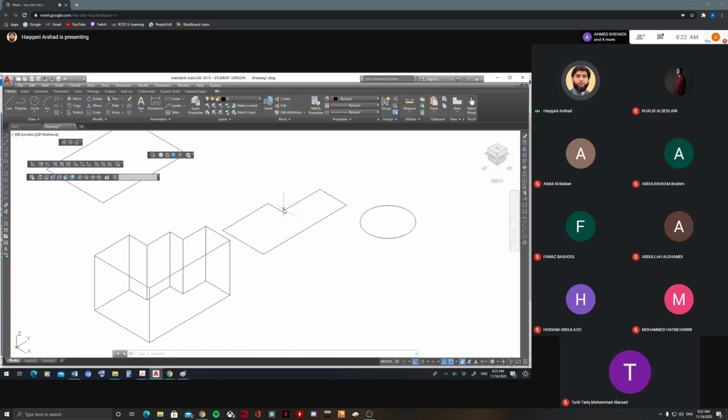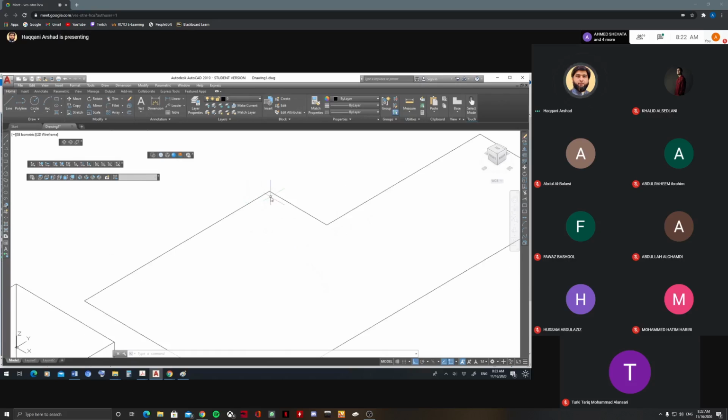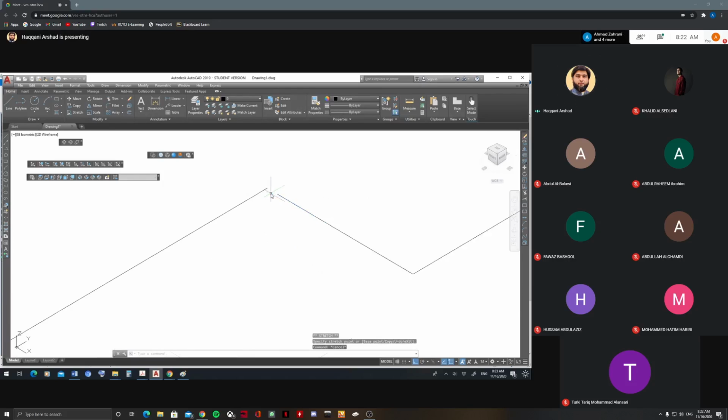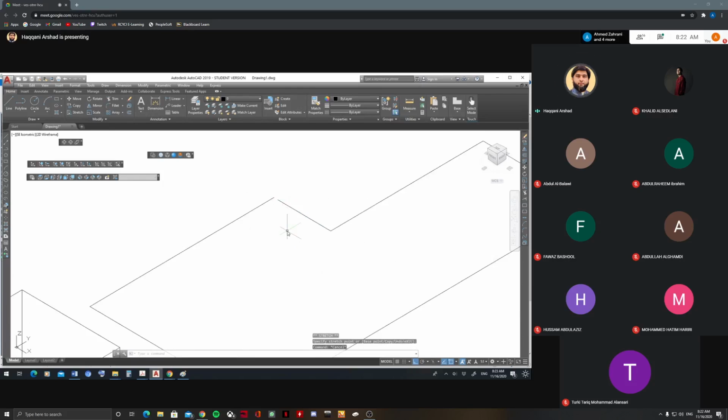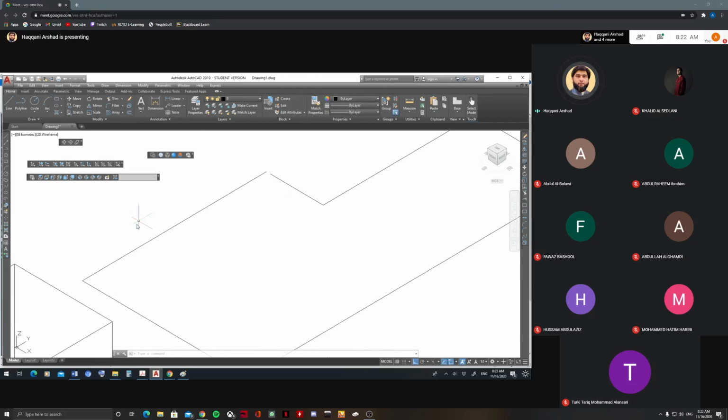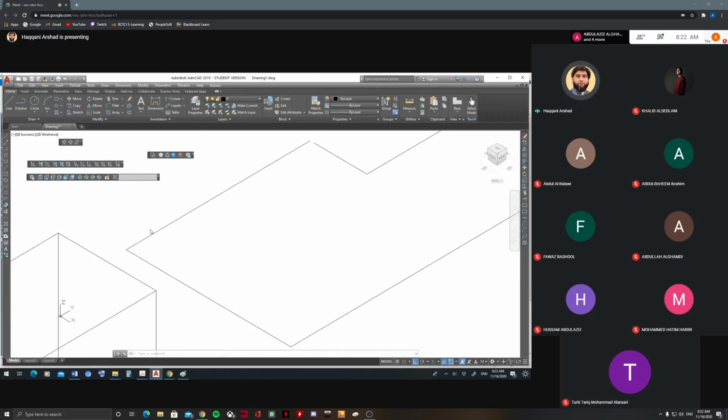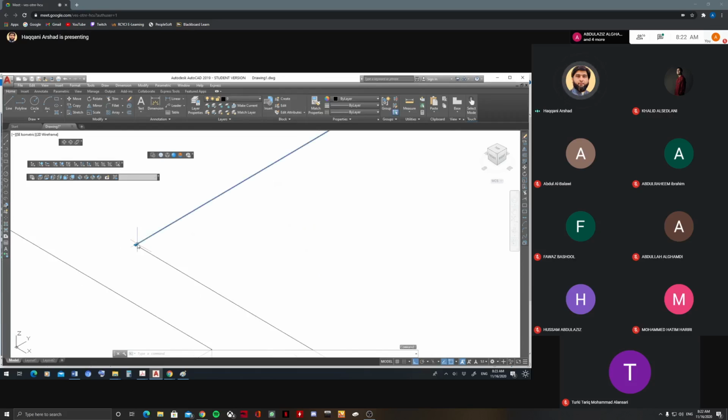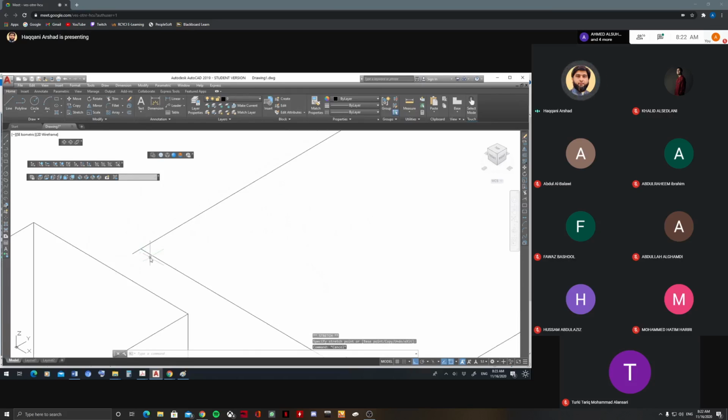It must be closed from all sides. Like for example, if one line is not properly closed, if you have a gap like this, extrude will not work. And sometimes you have double lines, many lines, and if you trim and if you have edges, like you have a line going somewhere like this, in this case the extrude will not work.